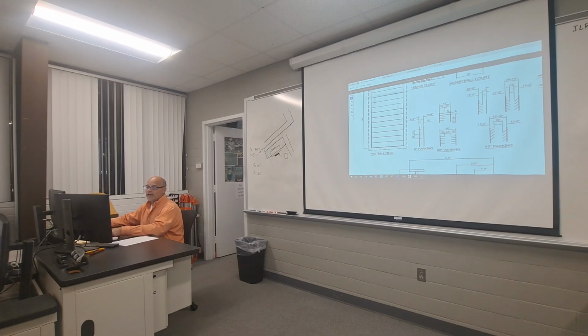So if you do 90-degree parking and it's one way, or just one lane of traffic right here, 18-foot parking spaces, 24 feet behind it to be able to pull in and out of that space, you need a minimum of 42 feet for one-sided parking spaces. That also carries over, that 42 feet also carries over to your handicap spaces.